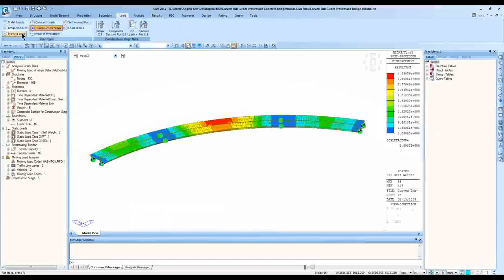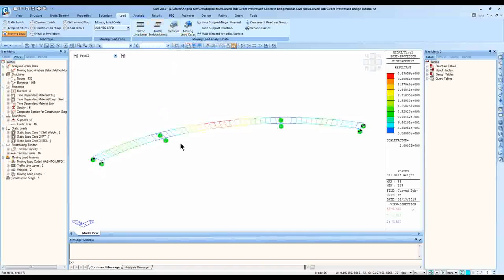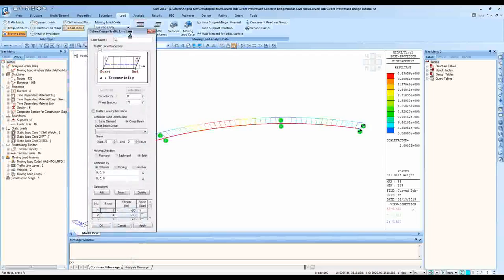So moving load also, more details about different cases, for flared or unique structures, will be covered in our moving load session. But today, for the moving load, you can define in 3 steps: define your lane, vehicle, and moving load. Since this is a structure with beam elements, I define line lanes. As mentioned before, I had defined 2 different lanes, lane 1 and lane 2.